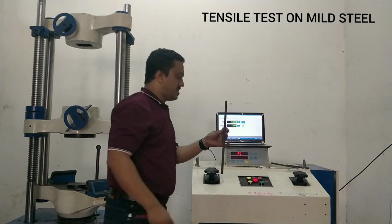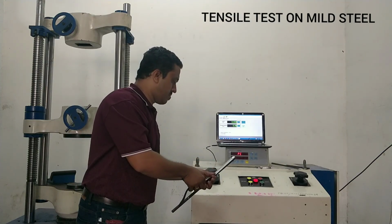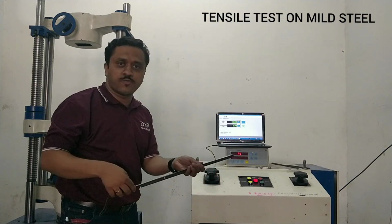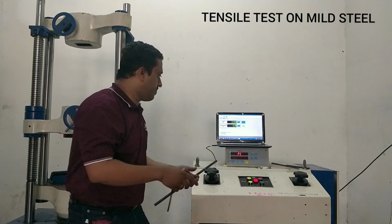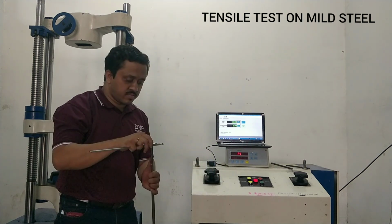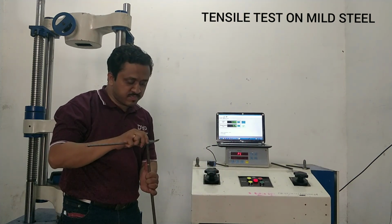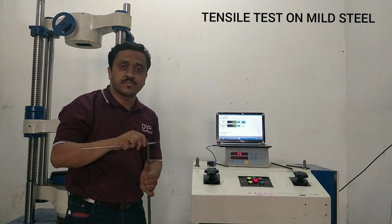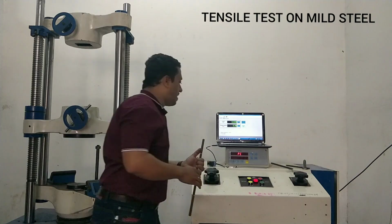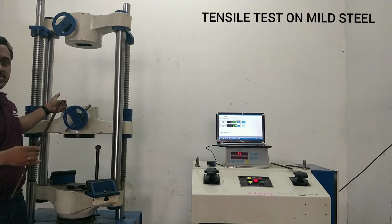Now we measure the length of this bar. The length of this bar is around 450 mm, meaning 45 centimeters. We will measure the diameter using the vernier caliper. So this bar has a diameter of around 12 mm, using the vernier caliper. Now we will fix this bar between the top and middle portion of this UTM.